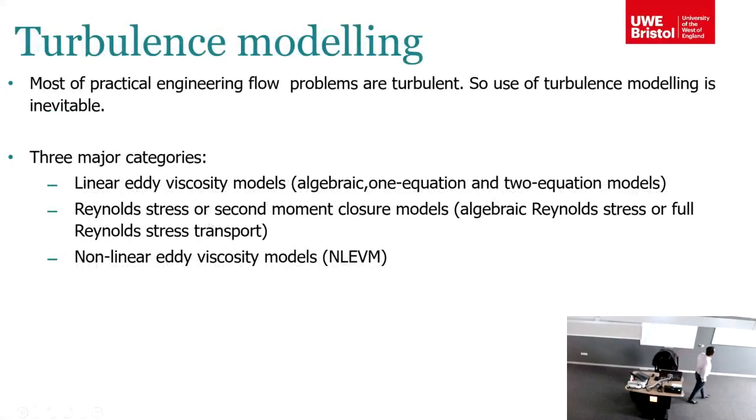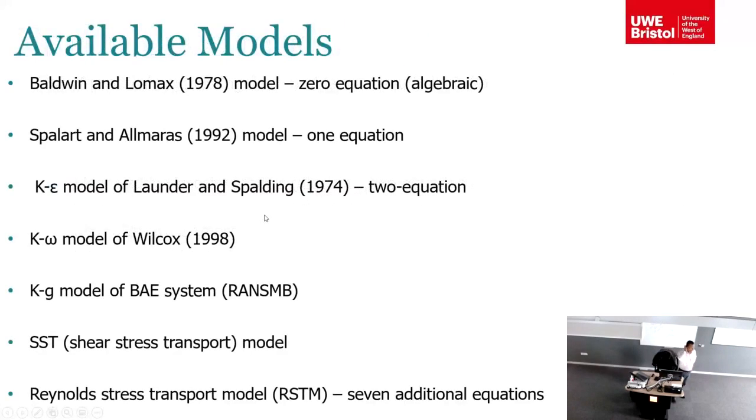And when you use turbulence modeling, you know the models: eddy viscosity models, Reynolds stress models, and non-linear eddy viscosity models. Eddy viscosity models are quite robust, and they are the most widely used ones. Available models are Baldwin-Lomax, Spalart-Allmaras, k-epsilon, k-omega, SST, and Reynolds stress models.